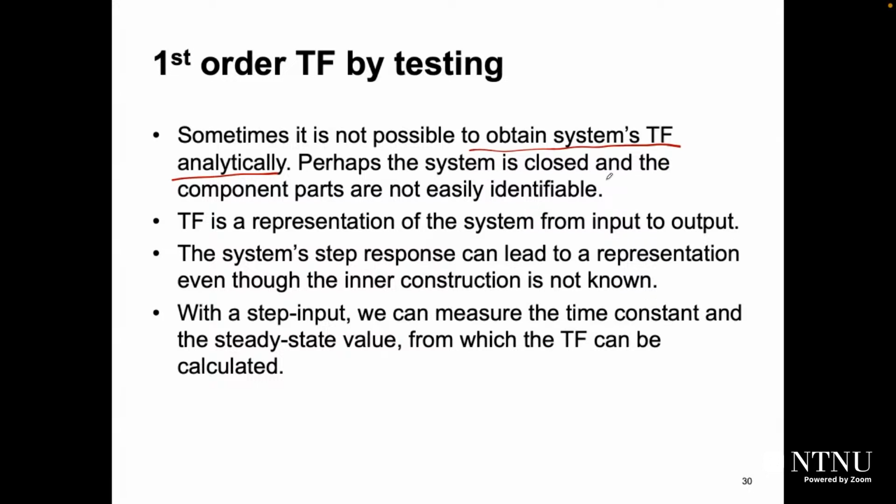Perhaps the system is closed and the component parts are not easily identifiable. Maybe you have a system in the lab from 1940 and there is no manual, no equations, no information about the system. If you try to open the system and analyze it to find its components, maybe you will damage it, or it's difficult to do. So in this case, we can try to find the transfer function by testing. The transfer function is a representation of the system from input to output. We will use a step response, which can lead to a representation of the inner construction, even if the inner construction of your system is not known.